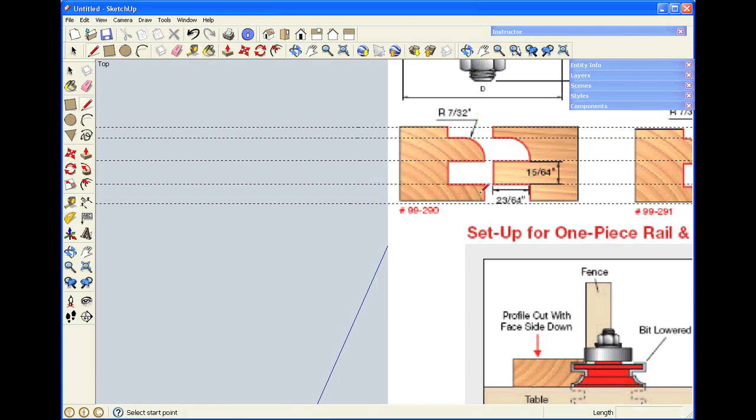So now I can take the pencil tool and draw along the lines I've already established with the guidelines. I know that this line should be 23/64 of an inch long, so I type in that dimension. I'll come down to where I intersect with the guideline, and then just trace over these points and hit the snap points that I want. I'm coming over 2 1/4 just as an arbitrary distance. I need a line coming down, and then I'm going to come over to this point,